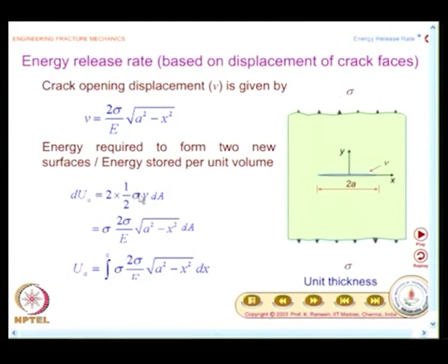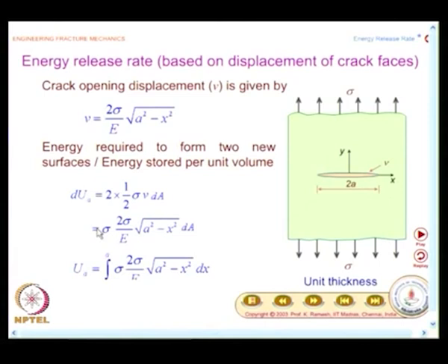We have looked at a thought experiment to justify that the force acting on the crack faces is sigma. This is the conceptual step. We have got the crack opening displacement. When I have to find the energy, I need to find the force and displacement, and it is quite subtle. To reconvince yourself that you have to apply sigma to open the face is very subtle. If you catch that, then you can write the expression for energy, then it is only an exercise in mathematics.